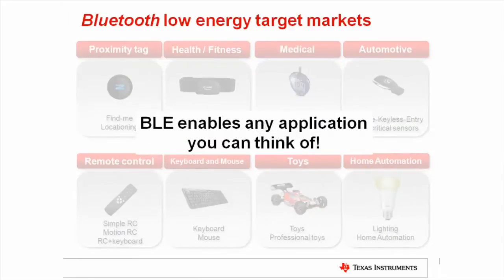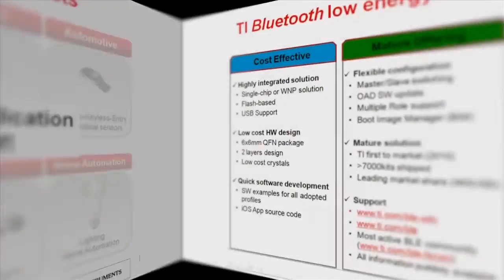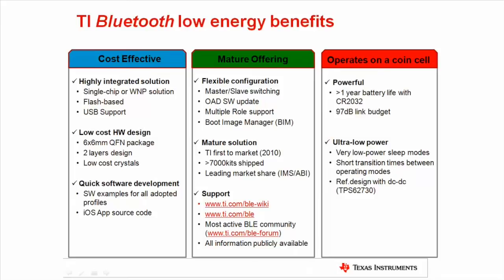In addition to the defined profiles from the SIG, every user can now make their own profiles. This opens up for any application you can think of. TI offers a complete solution for Bluetooth Low Energy consisting of complete hardware, stack software, hardware reference designs, and software development tools. By using a single chip, flash-based integrated MCU RF solution, you can get a very cost-effective yet flexible solution without compromising on the ability to update firmware in the field.